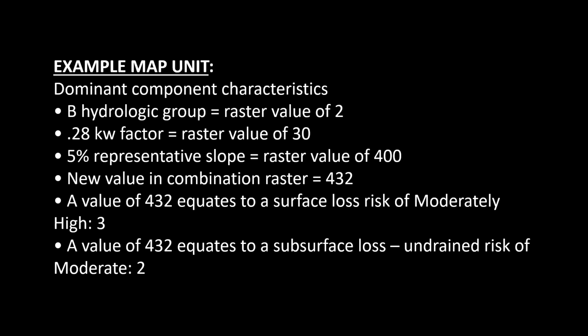Given that the definition of surface runoff vulnerability places more emphasis on slope than does the subsurface loss vulnerability, which emphasizes hydrologic group over the other primary variables, more differences will be observed for surface loss outputs when comparing the map unit versus pixel-based approach.